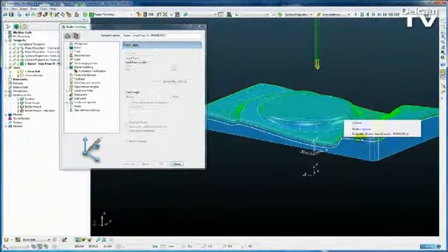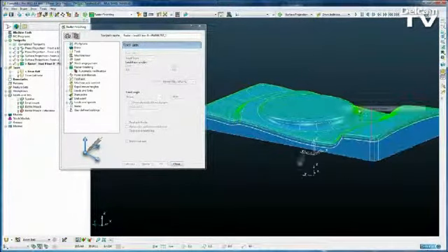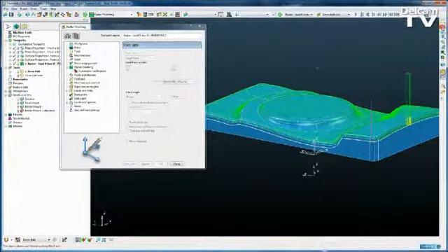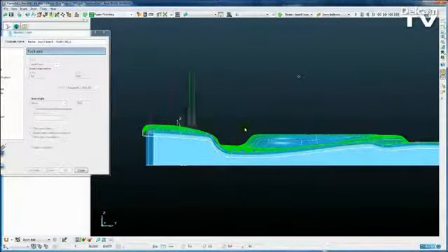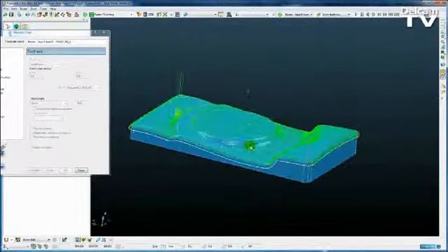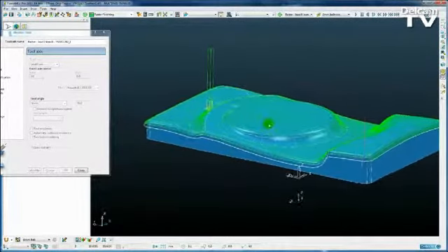So if I attach the tool to the toolpath and simulate it, you can see when we look from the side, the toolpath is vertical at all times, and that's because the preview plane was flat in the XY plane, and that's just projected straight down in Z. But now, with the ability of Toolpath Mode, we can convert this into a surface normal lead and lean toolpath.